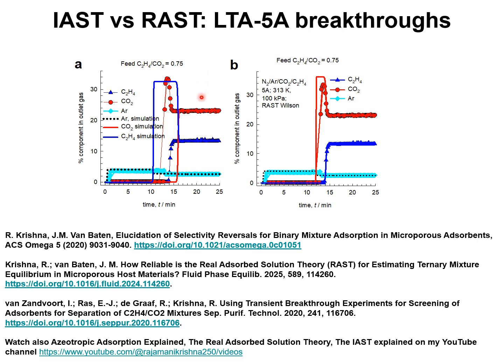For the breakthrough experiments with LTA-5A zeolite as adsorbent, using a feed mixture in which the ratio of C2H4 to CO2 in the feed mixture is 0.75, I compare the breakthrough experiments with breakthrough simulations in which the mixture adsorption equilibrium is determined using the IAST.